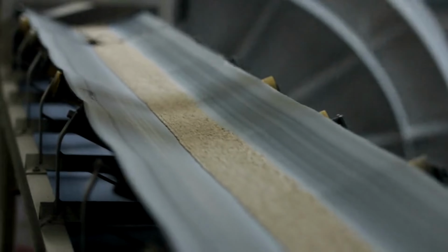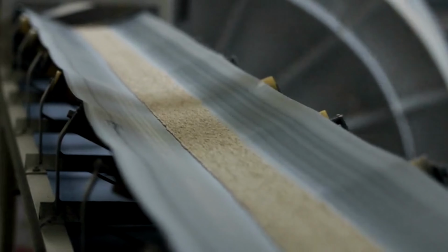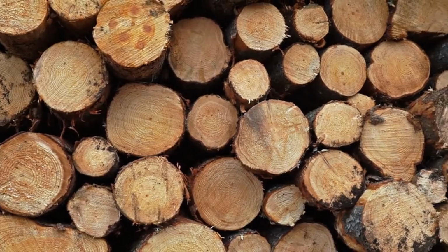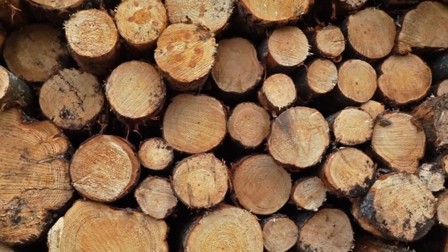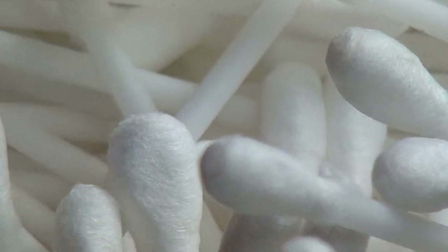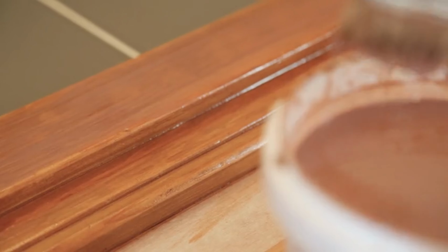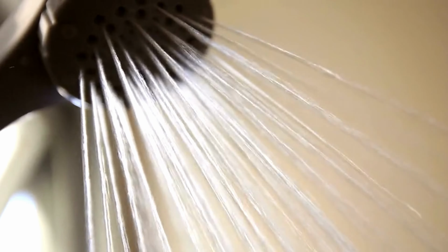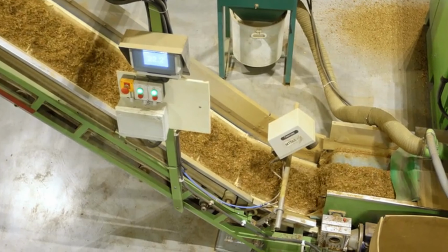1. Advanced wood processing and fiber sourcing. The quality and type of paper produced depend heavily on the fiber characteristics. A. Wood selection and optimization. Different wood types impact paper properties. Softwood, such as pine, spruce, and fir, gives long fibers and high tensile strength, used in packaging and tissue. Hardwood, such as eucalyptus, birch, and poplar, gives short fibers and a smooth surface, used in fine printing paper. Mixed fibers give balanced strength and smoothness. Mills use computerized sorting and blending to optimize fiber quality.